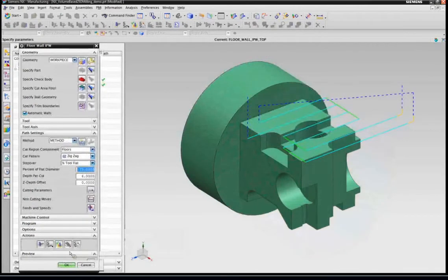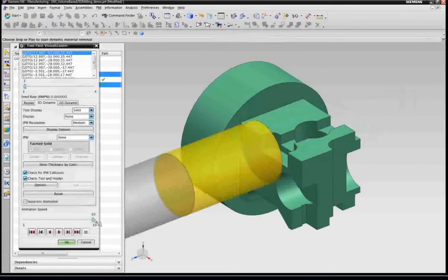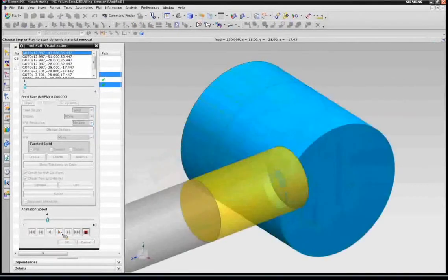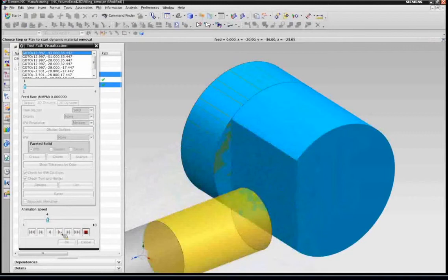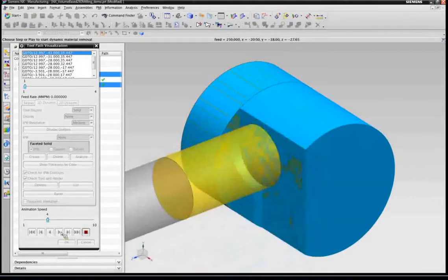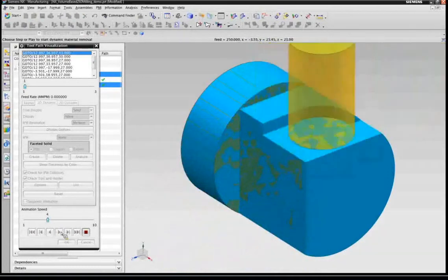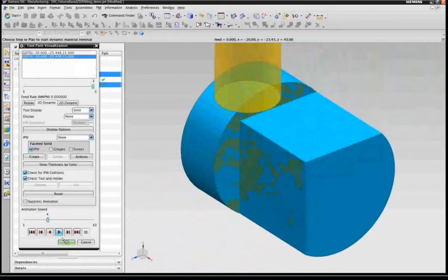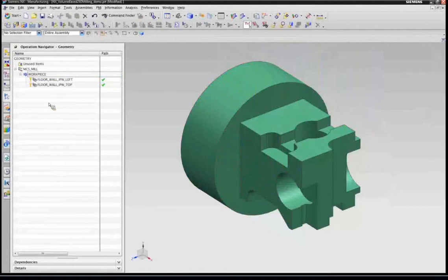And if we just quickly show what we've done on those first 2 operations using a toolpath verify, then I'm optimistic that you'll understand what we're trying to do when we say this is really looking at the in-process workpiece. So I'm going to cut the left portion of the part first in 3 cut levels without cutting any air whatsoever, and then I'm doing my roughing operation on the top, exactly 2 cut levels, and I'm leaving a mil of floor stock. So that's the basic principle of this operation.